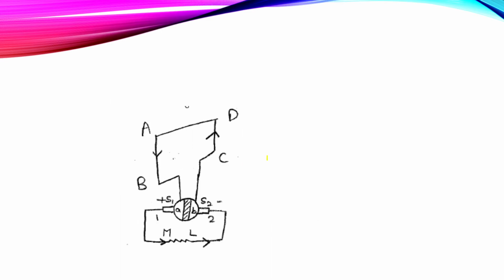So, coming to the next figure, I'll explain the direction of the current. S1 and S2 are two slip rings that are connected to the circuit. As the coil continues moving in the first half revolution, no EMF will be induced at position 1, maximum EMF at position 3 and no EMF at position 5.